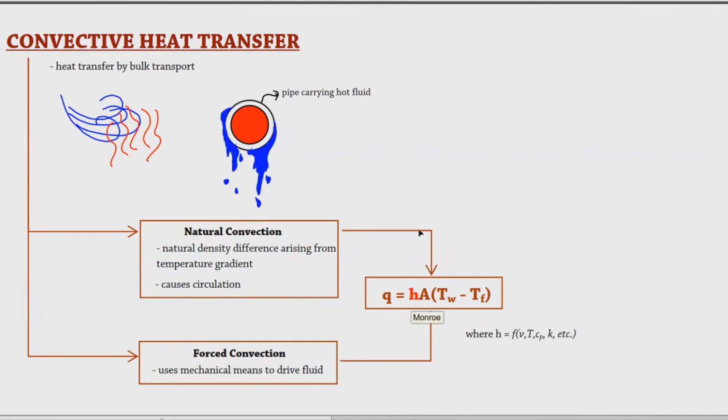coefficient. Before, we were dealing with thermal conductivity for conduction; now we'll be calling something like a replacement for k, but not the actual replacement, but something that gives you the resistance. So this is what we call h now, or the heat transfer coefficient. And then this is the area of contact, and then we have Tw minus Tf. Tw is based on our heat generation. Tw is the temperature on the outside surface of the material, and that's the same thing for convection.